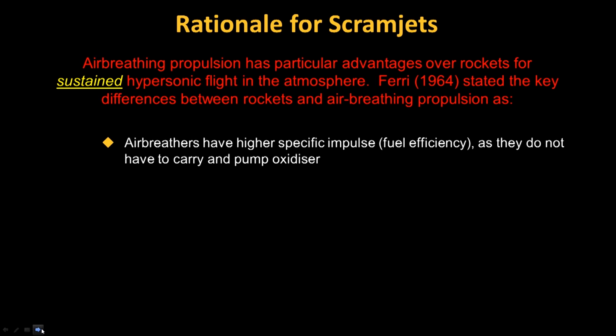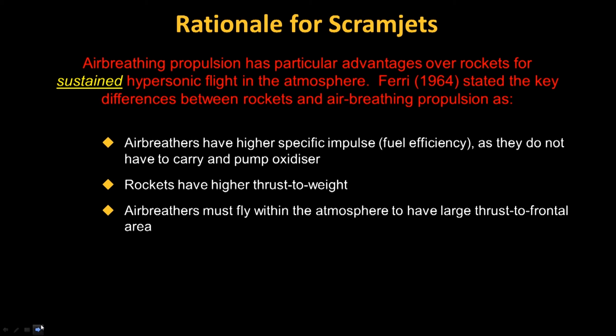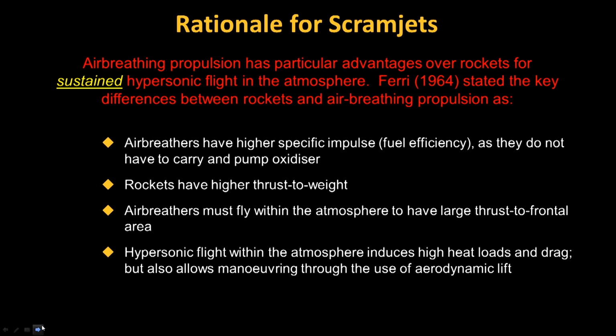Air breathers have higher specific impulse or fuel efficiency, as they do not have to carry or pump oxidizer. Rockets, however, have a higher thrust to weight. Air breathers must fly within the atmosphere to have large thrust to frontal area, as the air breathing system requires airflow. Now, hypersonic flight within the atmosphere induces high heat loads and drag, but it also allows maneuvering through the use of aerodynamic lift.